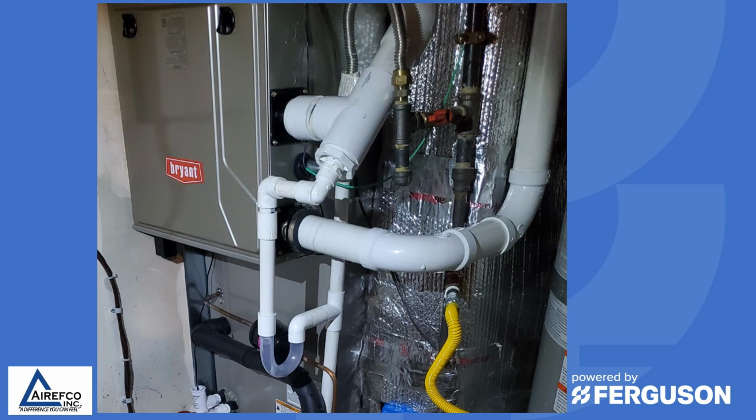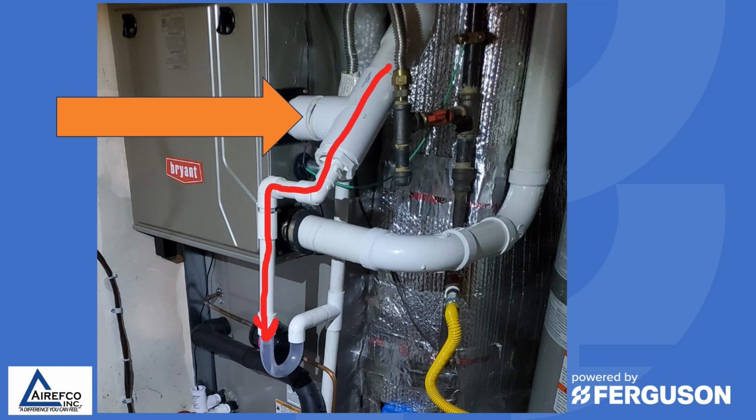In this video, we're going to focus primarily on venting a 90% furnace, as there are many different ways that a 90% furnace can be vented. Many technicians feel that they have to get as much condensation out of the vent as possible before it gets back into the furnace. This is commonly done on the intake side, where the combustion air is being drawn from the outside. In this particular fitting, you notice that the condensate is being taken out of the combustion air pipe before it enters the furnace.